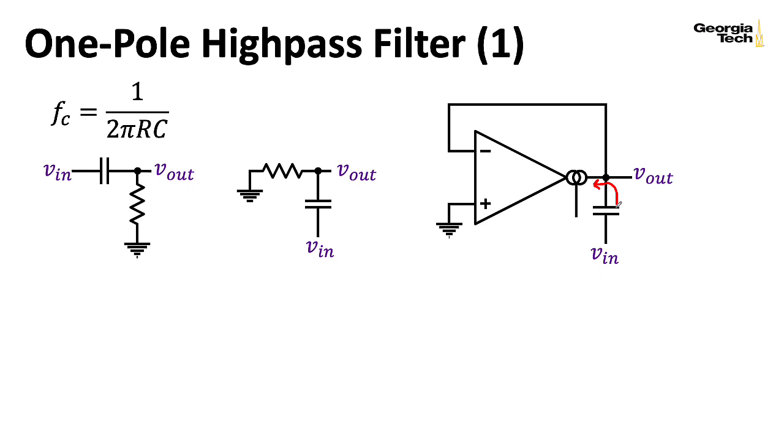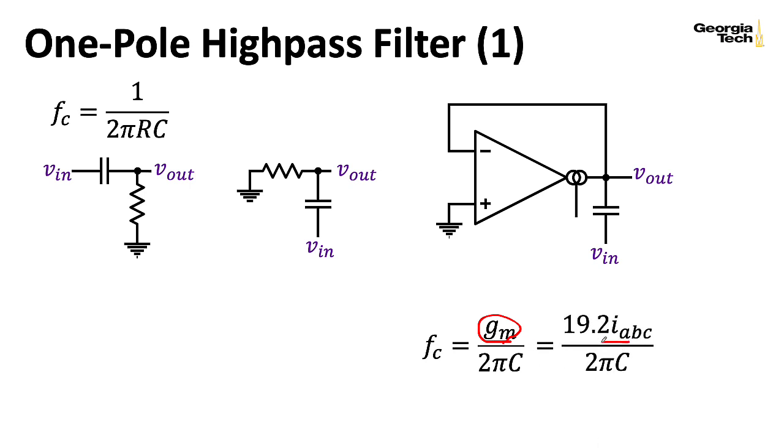They're equivalent either way. And once we've made that OTA replacement, we've replaced 1 over RC with the transconductance gain, which in practice we've generally been writing as 19.2 times the input control current. This 19.2 is sort of a typical 77 degrees Fahrenheit, 25 degrees Celsius, 298 Kelvin. Some people commenting on the last lecture pointed out that Kelvin is just Kelvin, it's not degrees Kelvin. But as we saw in the last lecture, this can slide around a bit, but we generally make this kind of assumption when we're doing things like, say, figuring out what value of capacitor we want to use.